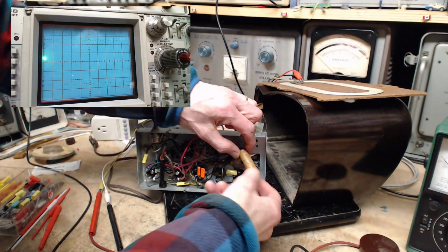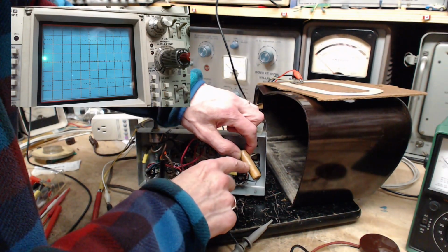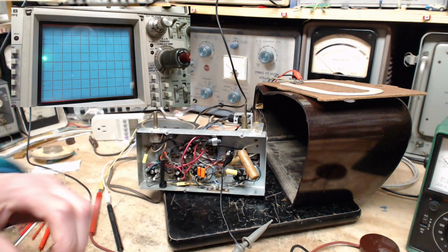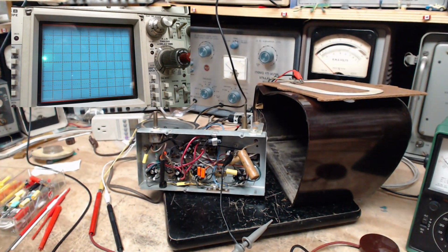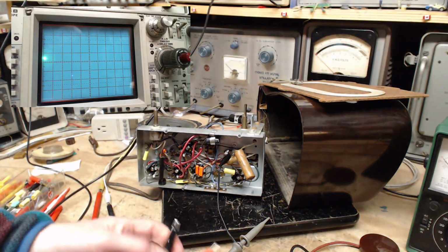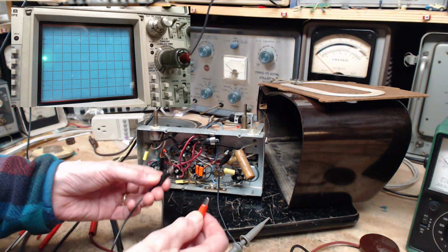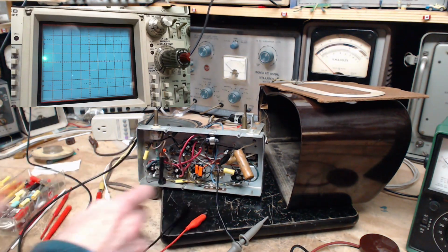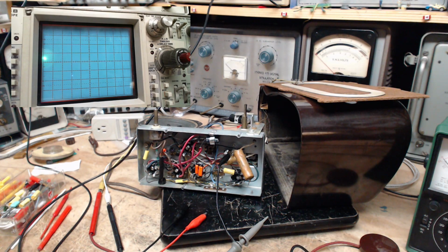Now, what does it say on it? Special. It says right on it, special. Okay, it's a special, all right. I think I'll repeat the very first thing I tried, which is to put the sweep across it. I wonder if I should have a resistor in series here. I think I need to put a resistor in series with this, otherwise I won't be able to see the variation. It won't be obvious.